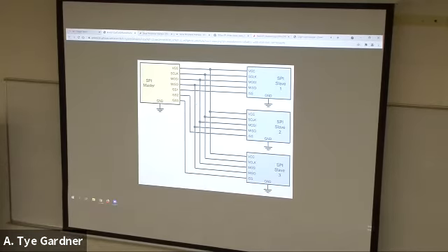You're not sharing chip select. So that's the downside, you have to have as many chip selects as you do devices. Yes, exactly. I2C, which we'll talk about later, does not have this issue. It does not have an extra line for every device.